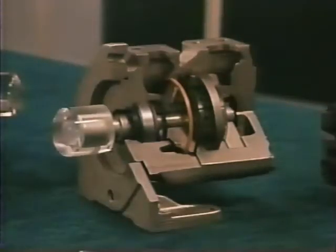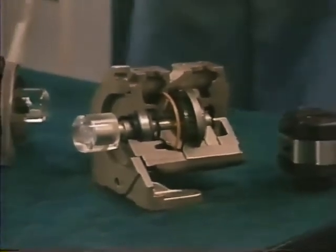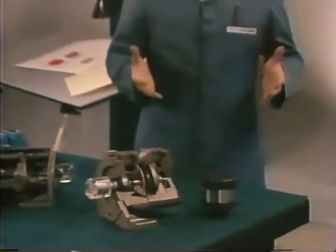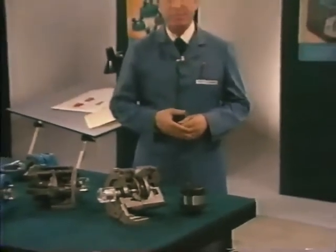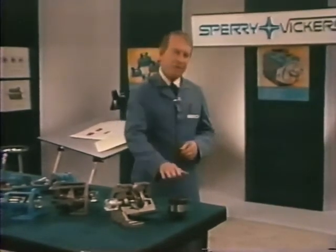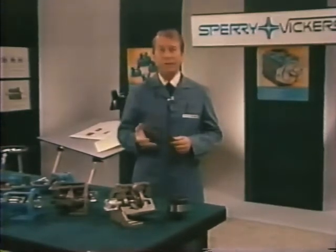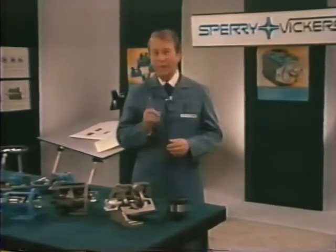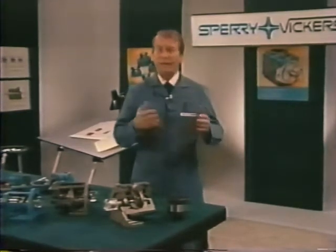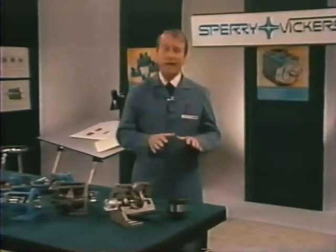Now we come to the third and final version, the Intravane series. This one is a truly high-performance unit with deliveries of 109 GPM and pressure to 2,500 PSI, 3,000 PSI in smaller units. It, too, is a cartridge-type pump, where the ring, rotor, and vanes are contained between a pressure and wear plate, held together by two small screws. These cartridges, incidentally, are available as pre-tested replacement units to speed pump overhaul and reduce downtime in the field.